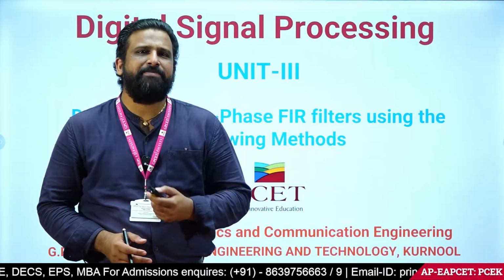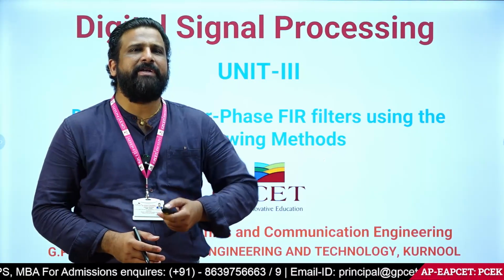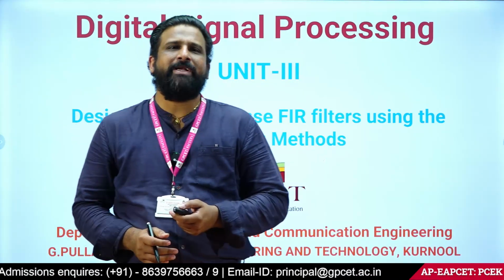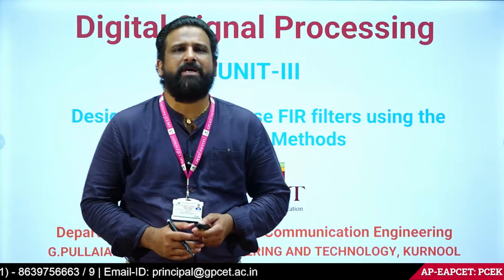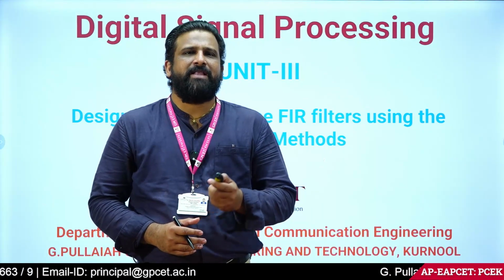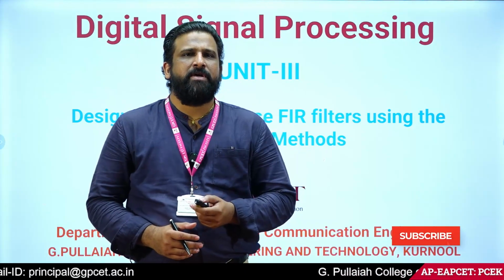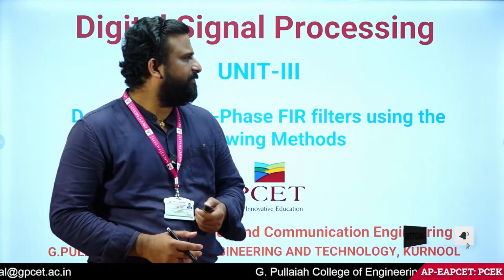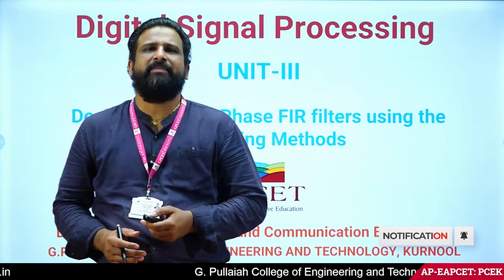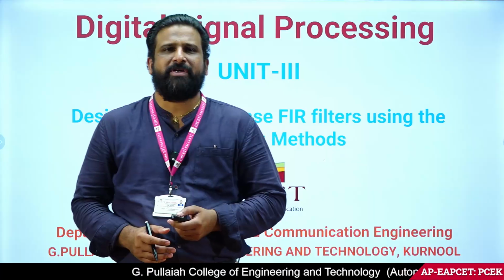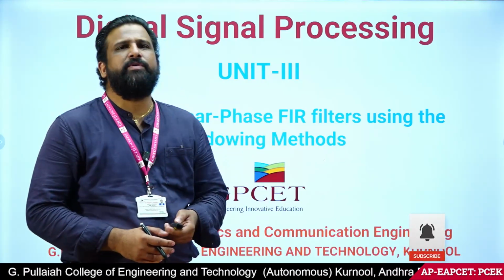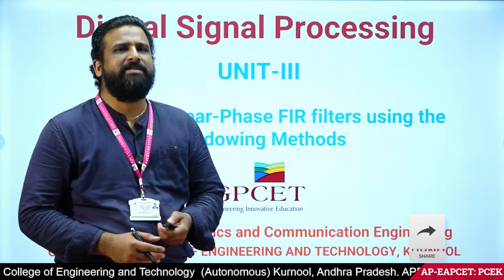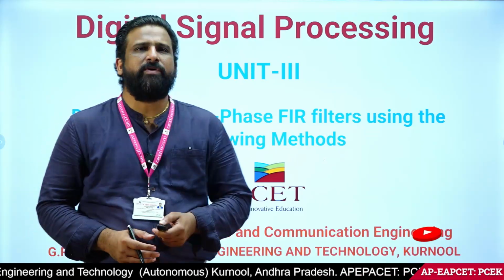That Gibbs phenomenon is overcome or reduced by using some windowing techniques. That means multiplying the desired frequency response with the windowing techniques, and the Gibbs phenomenon will be reduced. So let us discuss what is meant by windowing methods in this particular lecture, and how these linear phase FIR filters are designed using the windowing techniques.